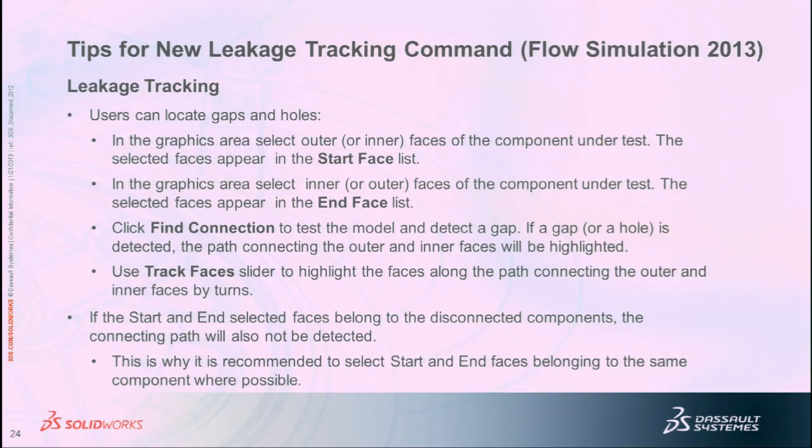For people who are not familiar, fluid mechanics or dynamics is a lot different than structure. In structures, you work on the solid part, so you always have the part there. But in fluid analysis, you're not working on an actual solid part unless you're doing heat transfer. You're mainly interested in everything else, the negative of the solid part. So flow simulation, and this is all done behind the scenes where people can't see, actually creates SolidWorks parts of all the fluid region. And this is true for internal and external.